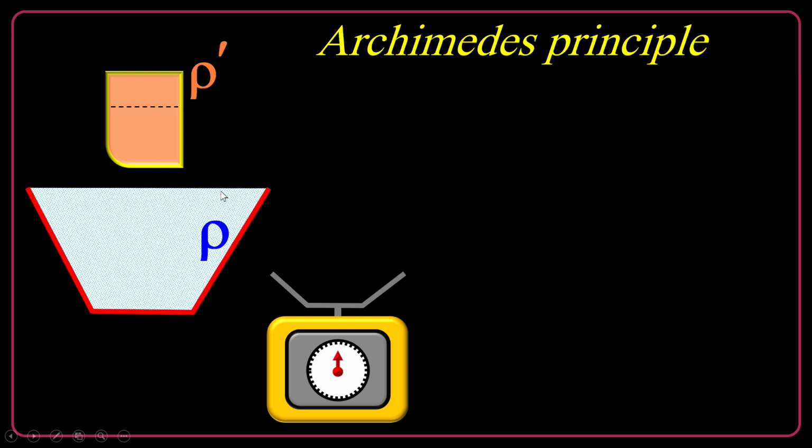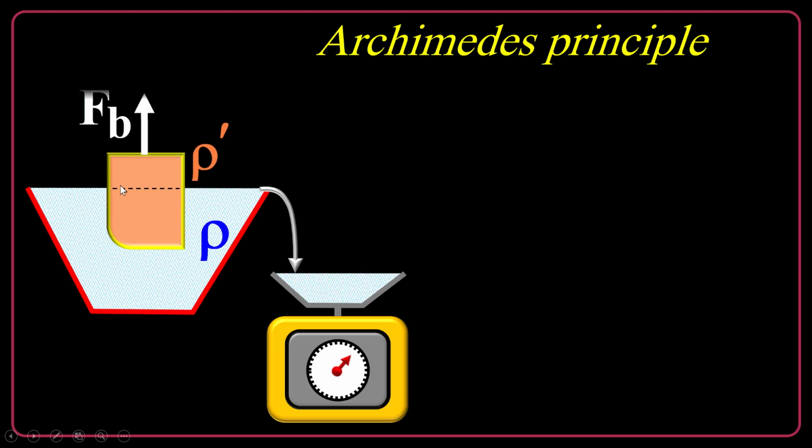And as the beaker is fully filled, the extra liquid, due to that submerging, is collected in the other empty beaker on the weighing scale. And this weighing scale can measure the weight of the displaced liquid. So I submerge the object and then I collect the extra volume, I mean the displaced liquid, and simultaneously I can measure the buoyancy force.